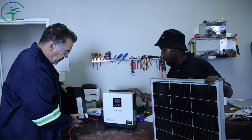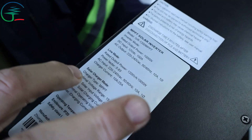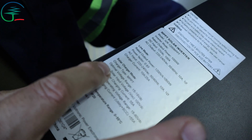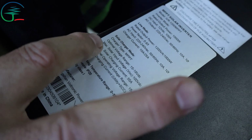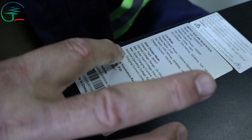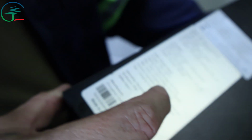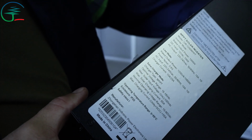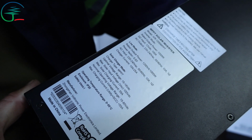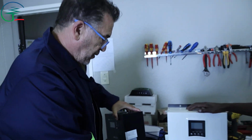I'll give you another example. Here is another inverter. If you look here, you see the solar charge mode. Here they won't call it the MPPT range. They call it the max solar input voltage, the VOC of 100 VDC. And here they put the max solar charge current of 55 amps. And this inverter has a rated output of 1000 watts.